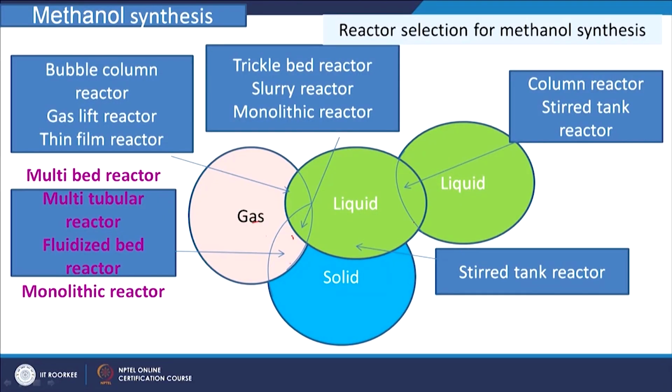In our case we have syngas, that is CO plus H2 in gas phase and then solid catalyst. So, we need gas and solid. So, this is our domain we have to choose. For these applications we get multi-bed reactor, multi-tubular reactor, fluidized bed reactors and monolithic reactor. So, these reactors are more suitable for the conversion of syngas to methanol.